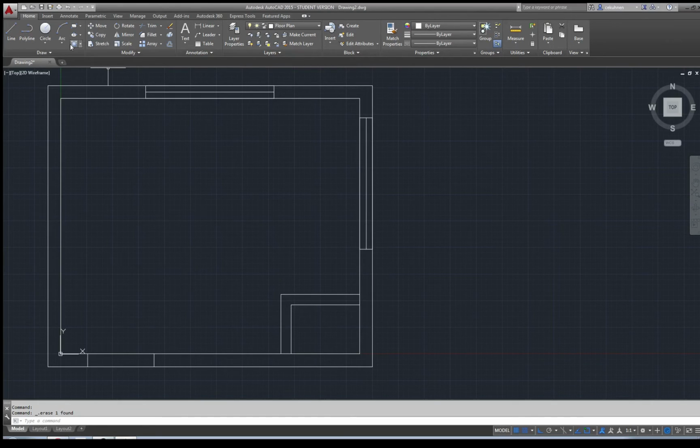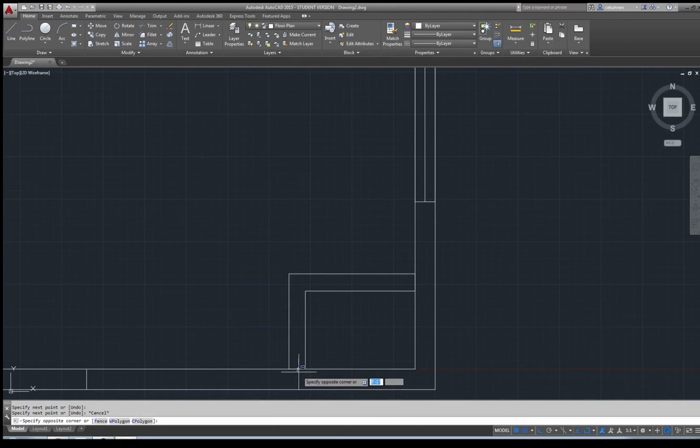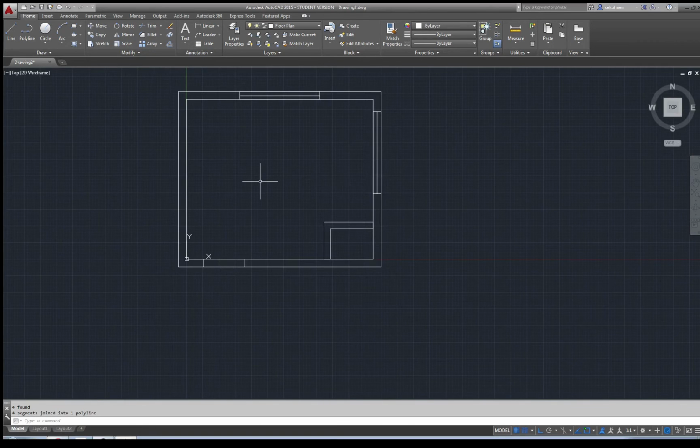So in this case, we're going to simply patch in missing lines at those ends with the snapping for endpoints and escape. And then those lines, see, I click, click, click, click, I join together into an interior wall. Okay.